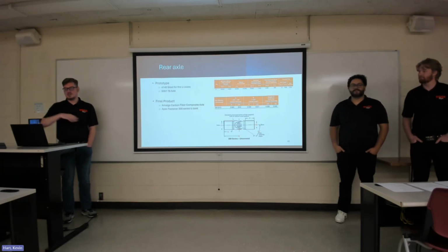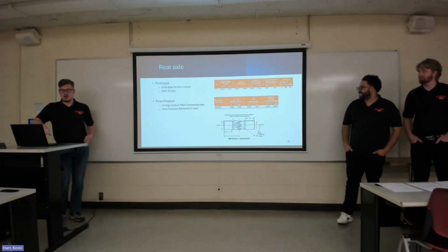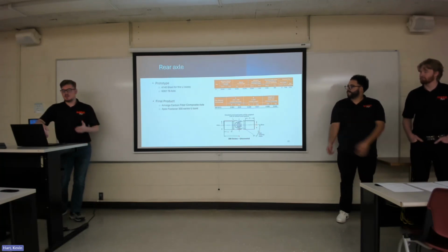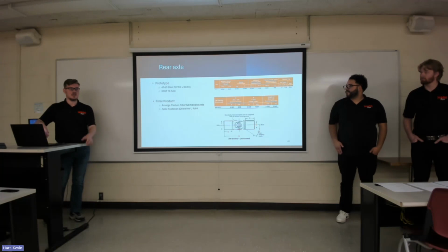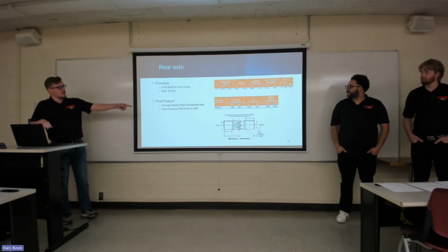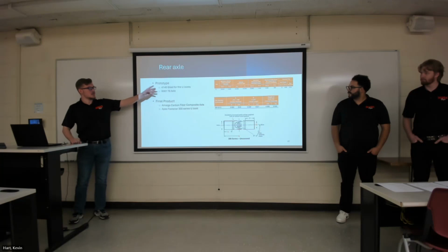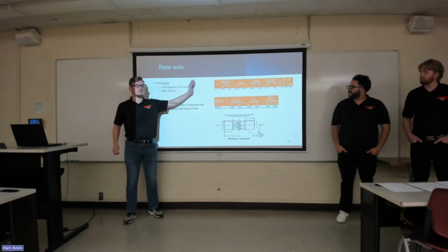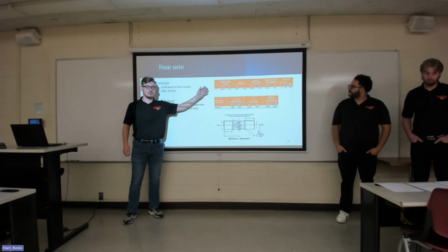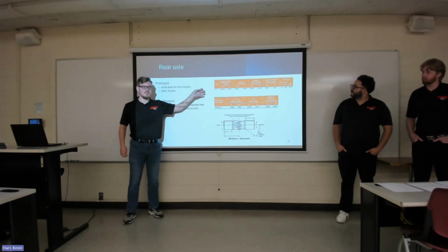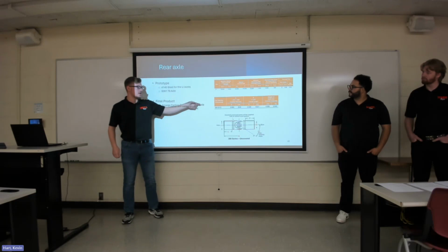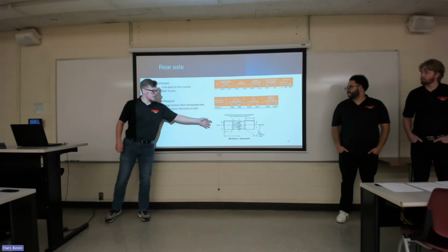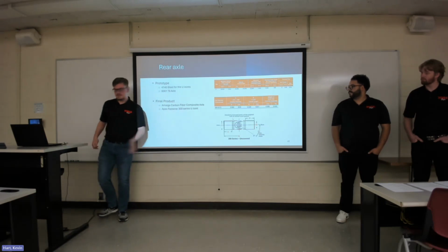The final product will be using Amalga's carbon fiber composites as our tubing for the physical axle, and we'll be using the 300 series of the Apex Fastener as shown below on the bottom left. The data sheets above here are just a description of what torsional and strength values these U-joints will be able to do from testing done by the supplier, as well as a description of what that U-joint is going to look like in terms of the outside diameters, overall length, and weights.